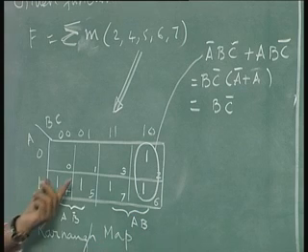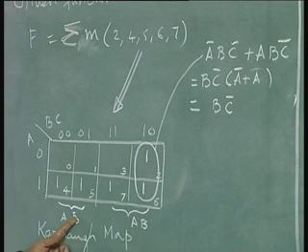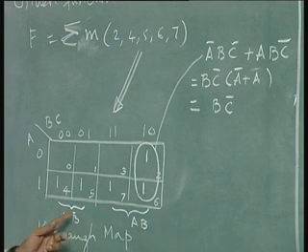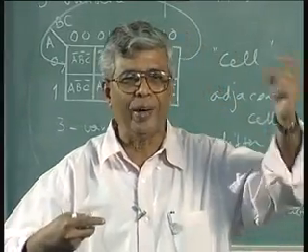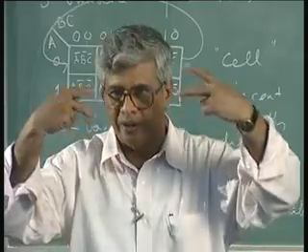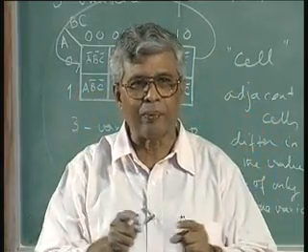But again these two cells and these two cells are adjacent. Here it is B bar, here it is B, A remains constant throughout. So, instead of doing it in 2 steps, grouping 2 ones and then combining them again in one more step, I can group 4 ones at the same time.